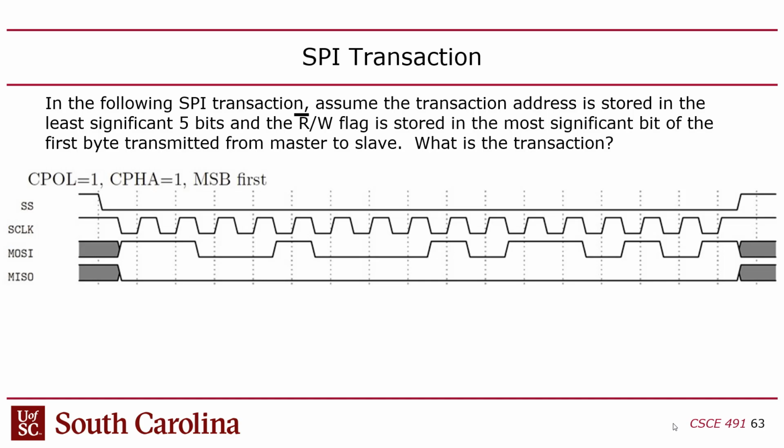That brings me to here, which means this must be the first bit of the data, right? So this should be the 9th cycle, 9th dotted line. 1, 2, 3, 4, 5, 6, 7, 8. No, it's here. Oh, I was wrong about that. So I guess it's 8? 8, sorry. 1, 2, 3, 4. That's the first 4 bits. Sorry, I was wrong. The address is actually not 4, it's 8. It's 1000. Then the data is 1011, which is B, 0101, which is 5, B5, right? So I'm writing B5 to address 8.